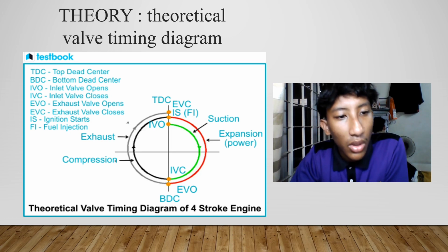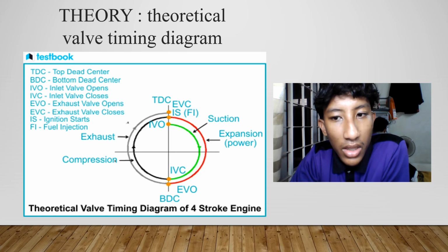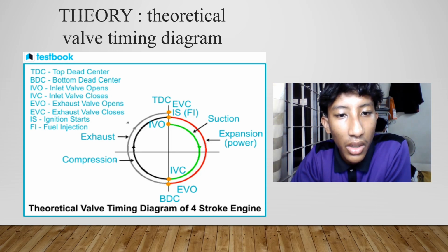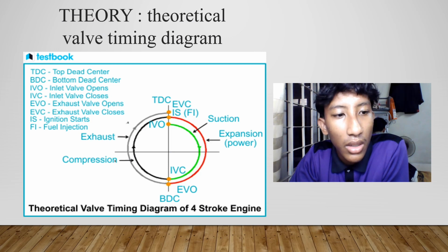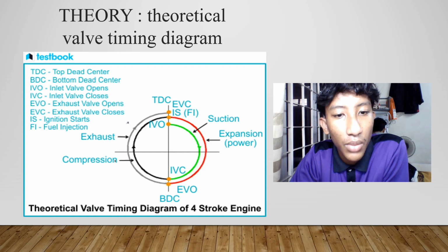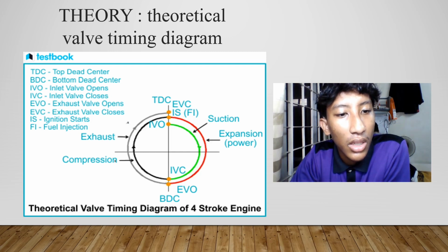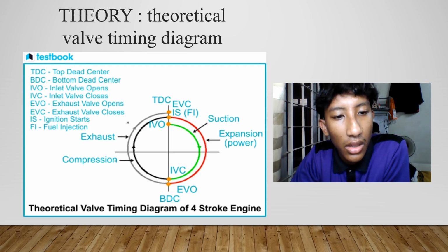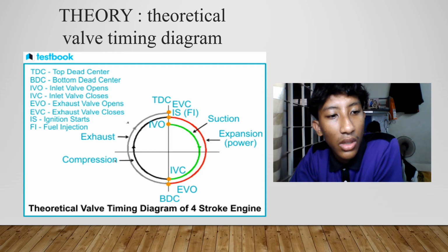It is important to note that in petrol engines, combustion occurs due to the spark produced by the spark plug, while in diesel engines, combustion happens due to high compression provided during the compression stroke, raising the temperature inside the cylinder to the ignition temperature of the diesel and air charge. In petrol engines, the air-fuel mixture enters the cylinder during the suction stroke, whereas in diesel engines, fresh air enters during the stroke, with fuel being sprayed by the fuel injector into the air.